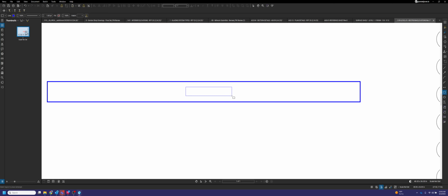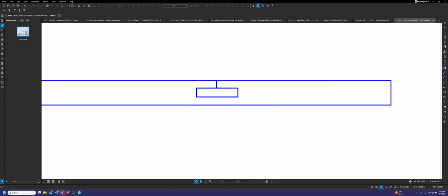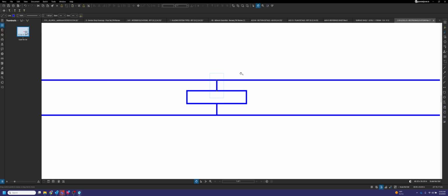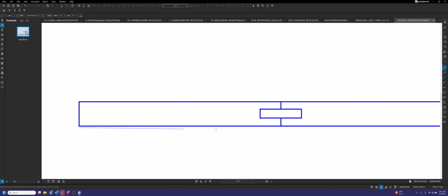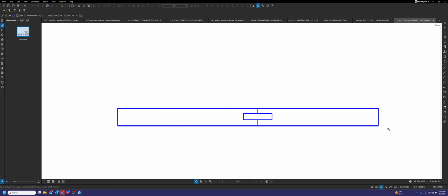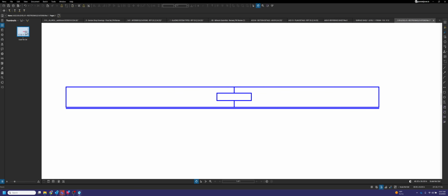So what that would look like is, let's say you have two panels that are shop joined together. Typically we'll put a spline or biscuit in between. A biscuit is a piece of wood that a woodworker will use to attach two pieces of material together. But if we have a shop joint, we'll have something more like this. We'll have that layer of veneer over the top, which is really thin. You won't actually draw that on your print, but just so you can visualize it, a shop joint is more like this.